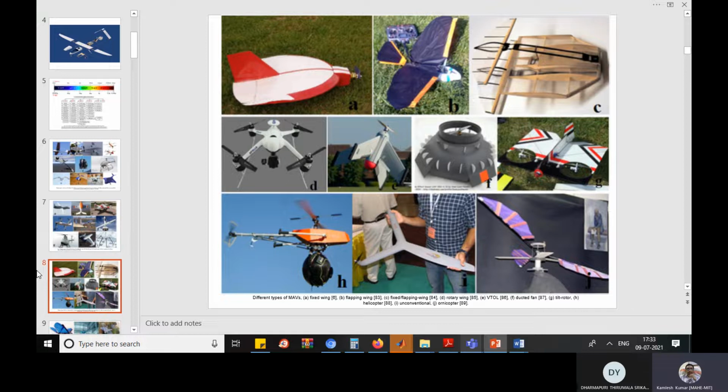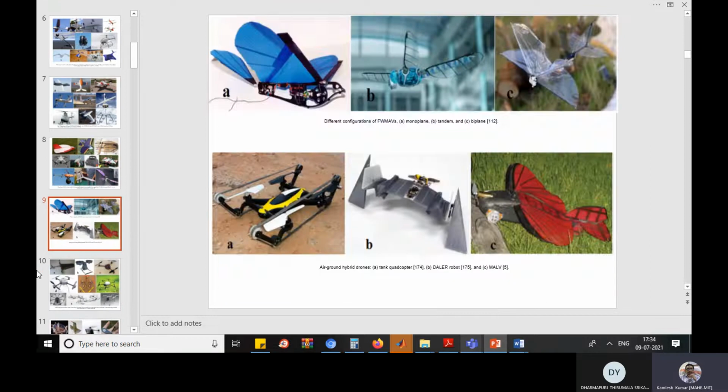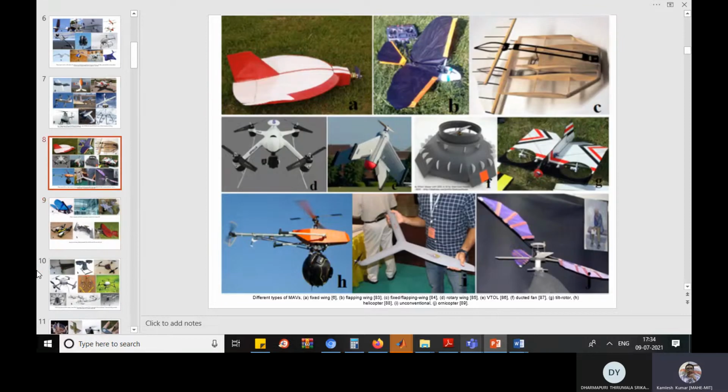That way you can go with designing at least one which includes your fixed wing as well as the multi rotors. Multi rotors can be detached in the future if required from a particular height, and the fixed wing is going to fly. So that much mass margin should be there. If the aircraft loses a particular mass during the detachment, then of course that should not affect the stability. So you can decide on designing one system with the detachment of the multi rotors, where the main platform is fixed wing, or going with different models and then attaching them. Okay, so this is the idea.